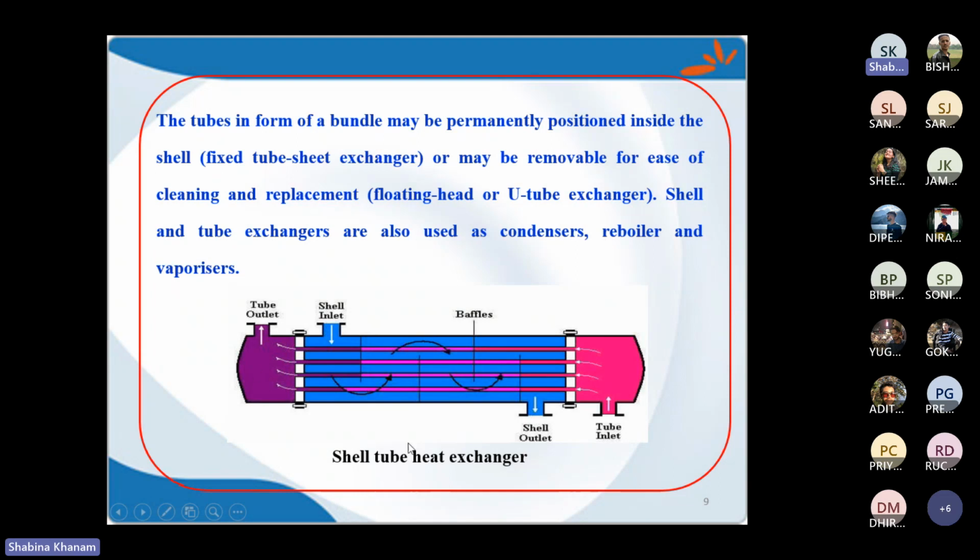Secondly, for the tube, this is the inlet of the tube where I have the openings, and it will be inserted in these tubes and exit from here. It means tube fluid will not have any chance to enter the shell side, and shell side fluid will not enter the tube side, and that happens because of this tube sheet.